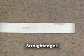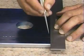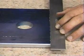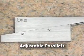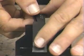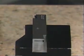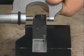Straight edges are flat lengths of tool steel or granite finished to extremely fine tolerances. They are used for scribing straight lines and to check surfaces for straightness. Adjustable parallels are employed widely in layout, gauging, and inspection, and expand into a range of widths. They are commonly used for comparing slot and opening sizes against graduated measuring tools.